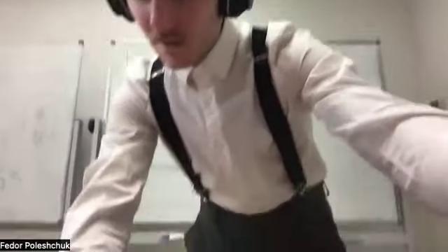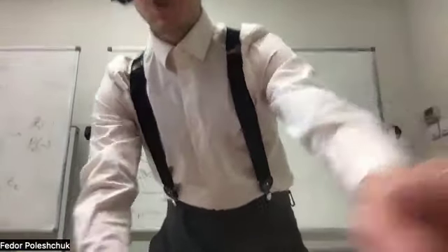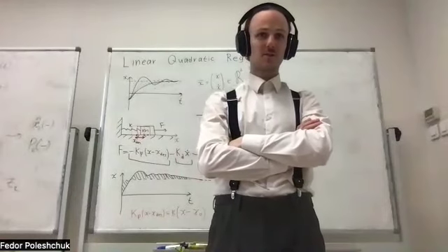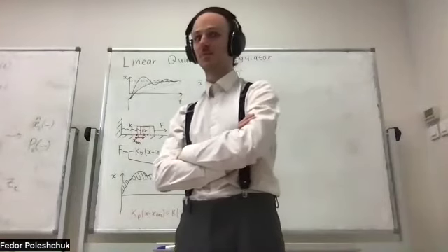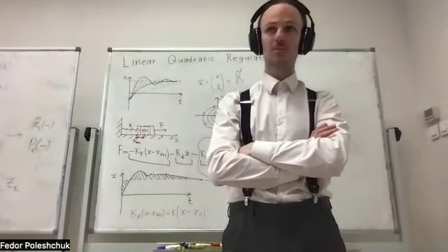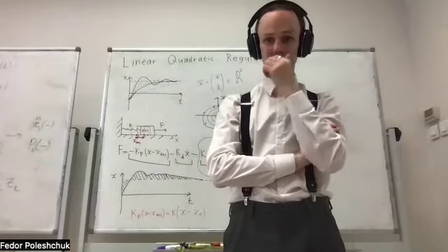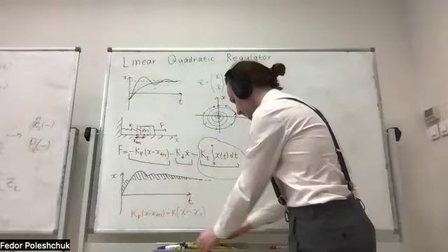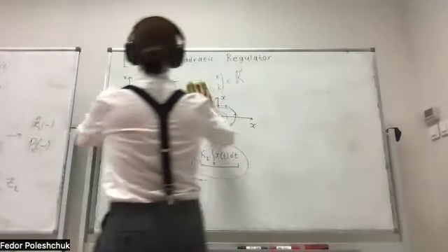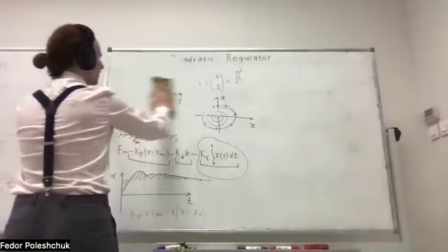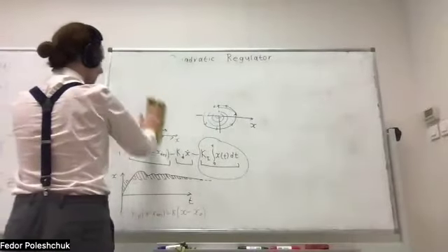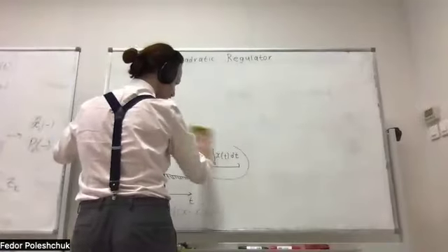So what are the drawbacks of the PID controller? It cannot account for any type of optimality of our control. If we want to, say, save effort, conserve energy, I mean, minimize the consumption, how can we do that with the PID? PID is just reacting to the current state of the system.